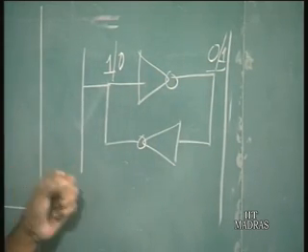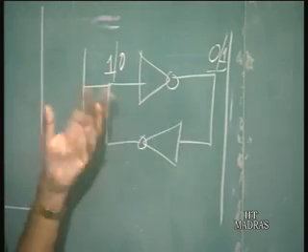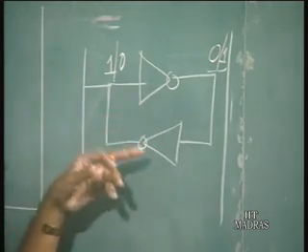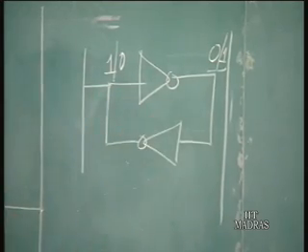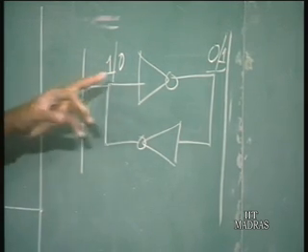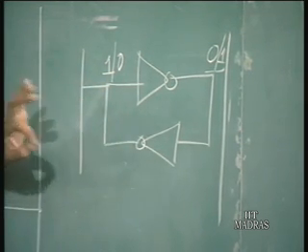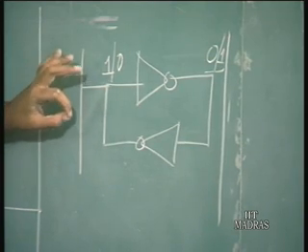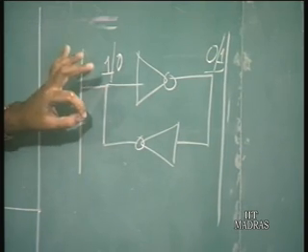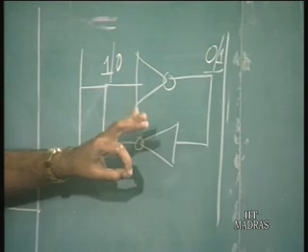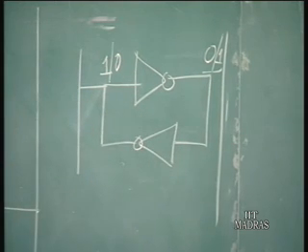which are stable. Okay. Now, if you have such a combination, it will always tend to go to one of these two possible combinations, and there is a large positive feedback involved. So, if it is maintained in an unstable condition, it will always tend to go to one of the two states which is favored.